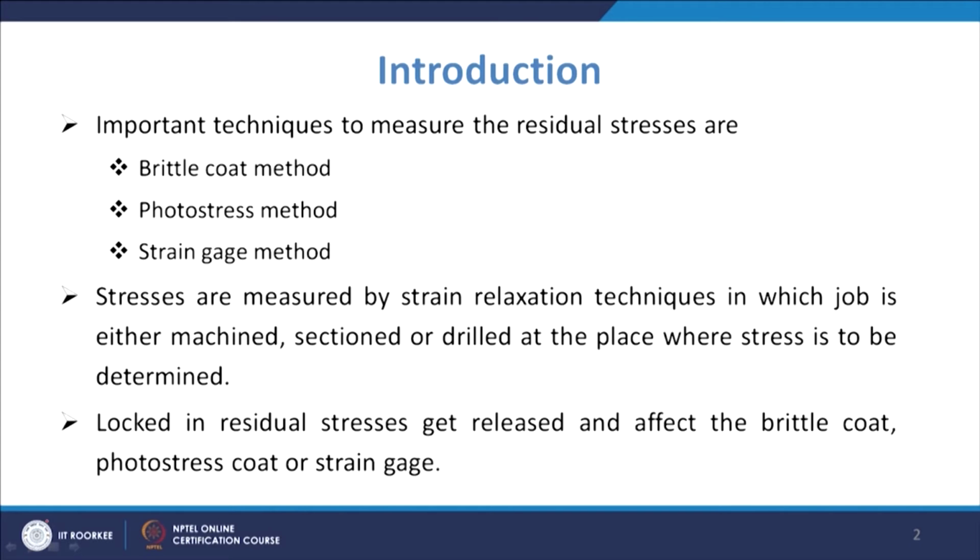What we normally do is use strain relaxation techniques. Either the job will be machined or drilled at a place where the stress has to be calculated, and accordingly we calculate these stress values.